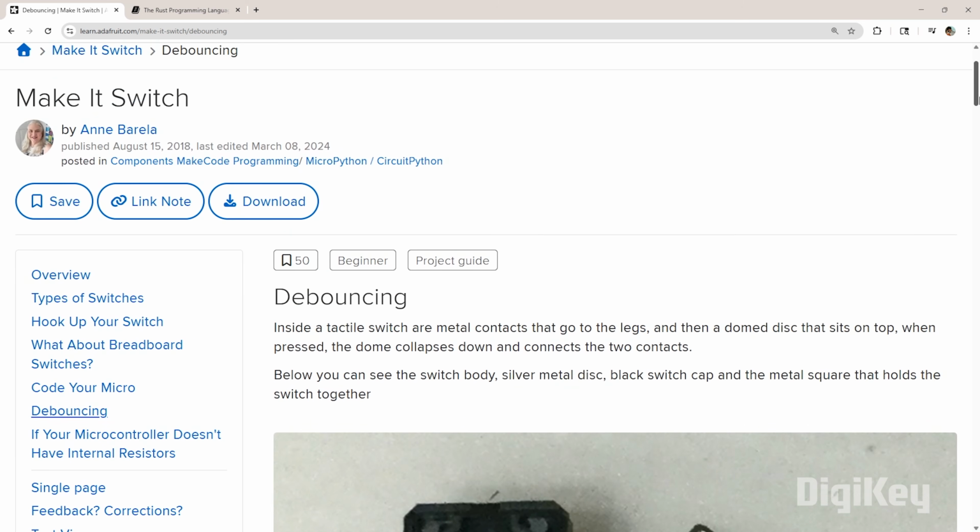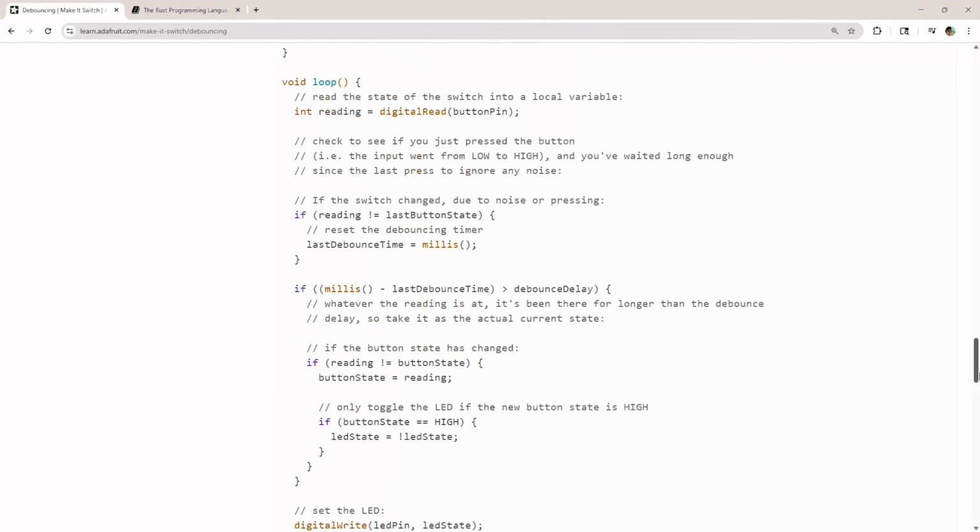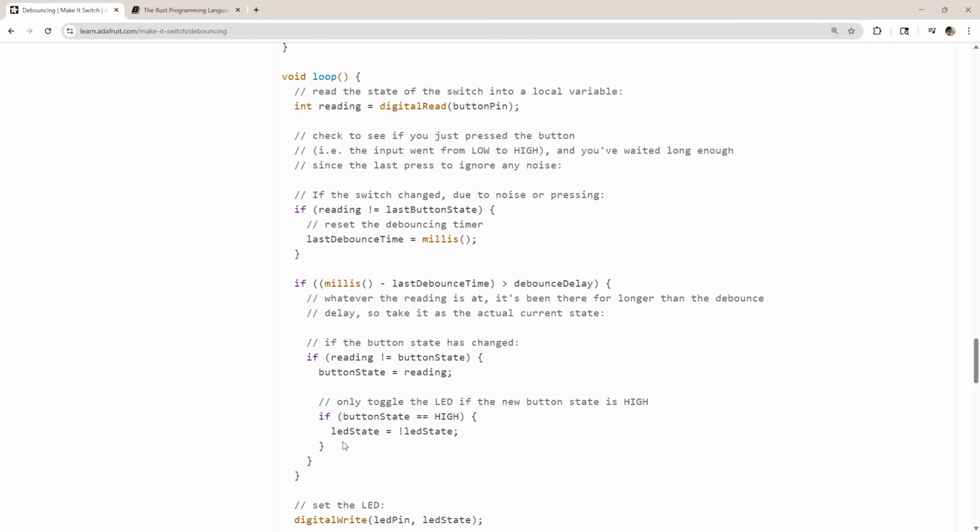You probably noticed that when you press the button, you'll sometimes get multiple readings. That's due to the button's contacts rapidly connecting and disconnecting on a single press, a common issue in the electronics world known as switch bounce. If you would like a challenge, try implementing a software debounce mechanism in your code to prevent multiple lines to the console on each press. Limor Fried has a great article on Adafruit's site that gives a good debouncing algorithm in Arduino code. Your job is to translate this to Rust for the I2C demo we just made.